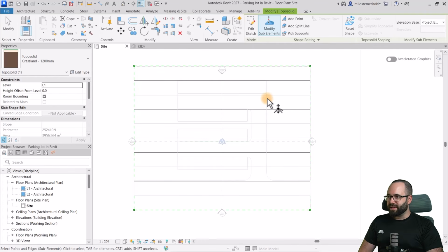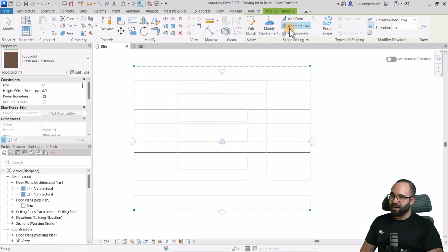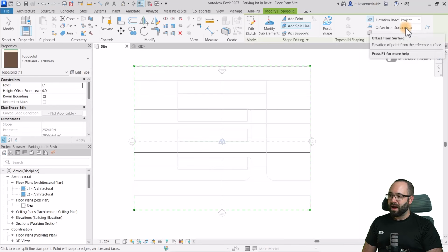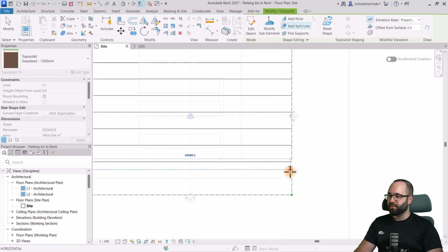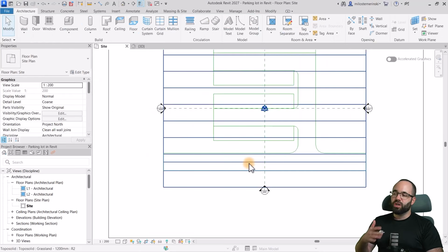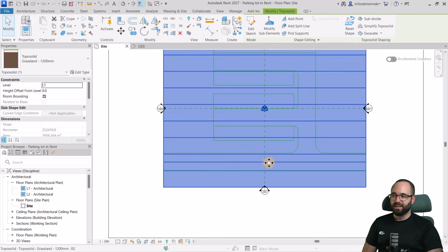What I like to do is mark out the center of the road, and then level it out by bringing it up on the lower side here and digging it in on the higher side. So what we're going to do for that is just use a split line. Now I prefer using this only for straight roads. So if you have a straight road like this, you just use a split line. I'm going to set this to a long surface with 0 offset, and then I'm just going to find the center of the road and click and go off to the other side. So we really didn't change the terrain in any way. We have just added this split line over here.